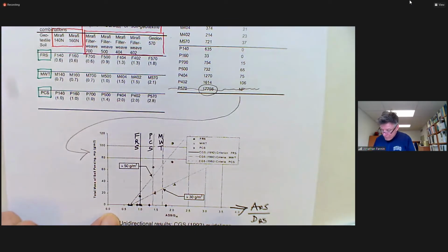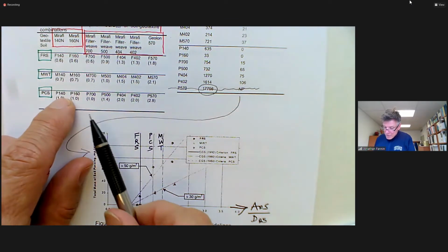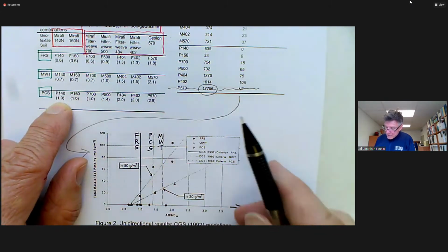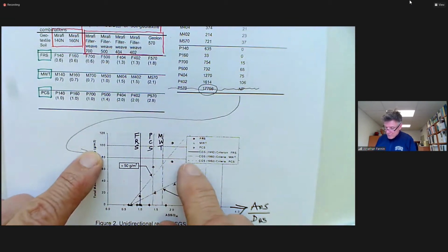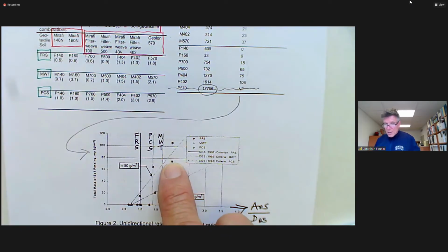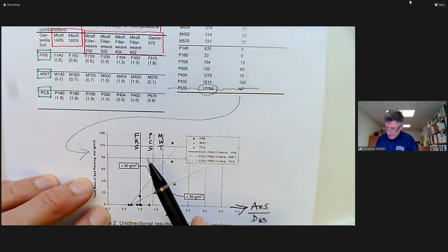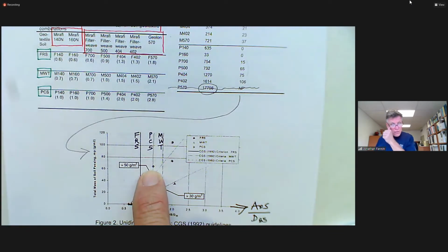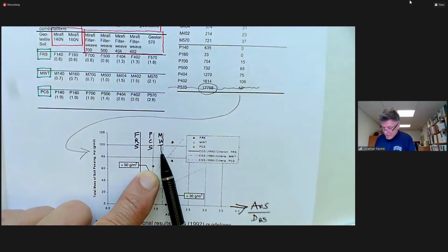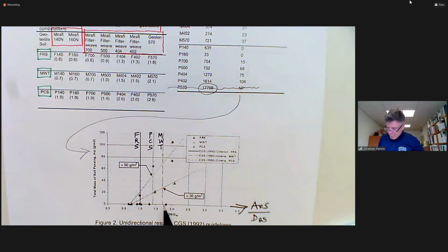If we look at the Port Coquitlam silty sand, the design guide says AOS over D85 should be less than 1.4. And the mass loss, as we go through from 1 through 1.4 to 2, we can see the mass loss here. Turns out to be of the order of maybe 50 to 100 grams per meter squared. Not a very significant amount of material. And thus it would appear there's a degree of conservatism, and the Canadian Foundation Engineering Manual criterion appears reasonable. And for the mine waste tailings with a ratio less than 1.7, those would be the triangular data, and there are the triangular data there.